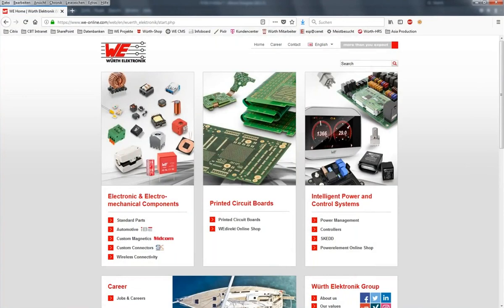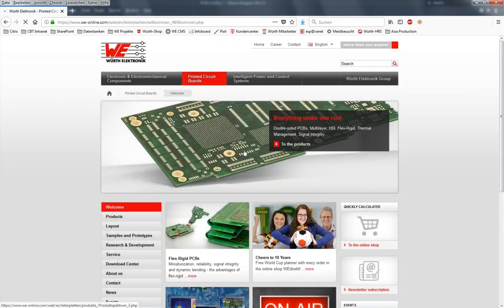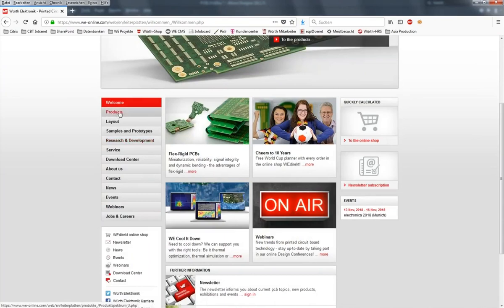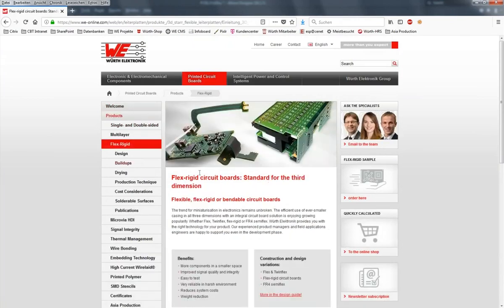Now there's a chance to have this much easier. We will show you afterwards. We are already providing the standards shown here. Besides the first stack-up, the 1FORI, this is a stack-up with only 1 copper layer. It's not possible to do this in the EDA tools, as they always require a top and a bottom layer. So you have to use a 2-layer construction and not use the bottom layer, for example.